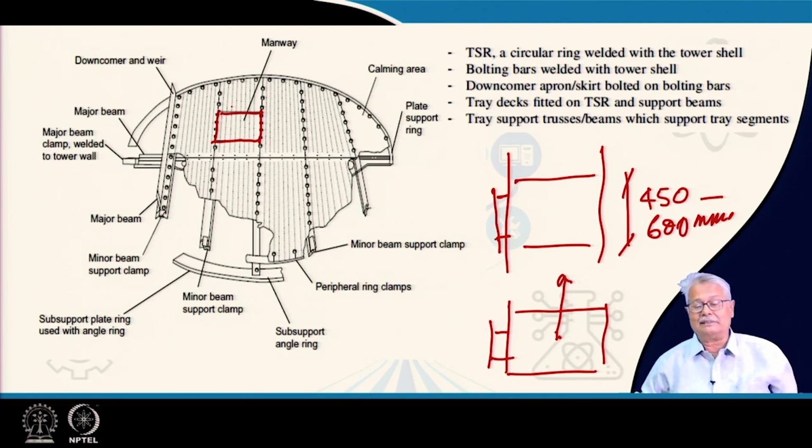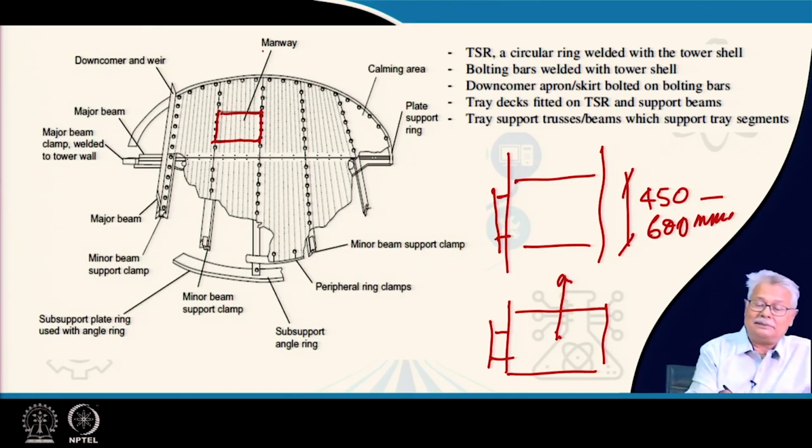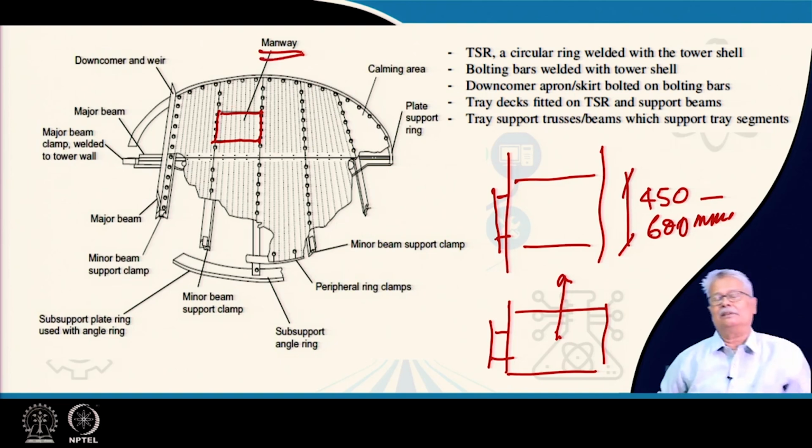Manholes are a very essential part, and typically you will understand the manhole size has to be such that it has to be also to pass through the manhole. What I meant basically is a manway, which typically is a square. The manhole size could be 20 inches, 24 inches or 22 inches. So, your manway size could be around 20 by 20 inches or something around that.